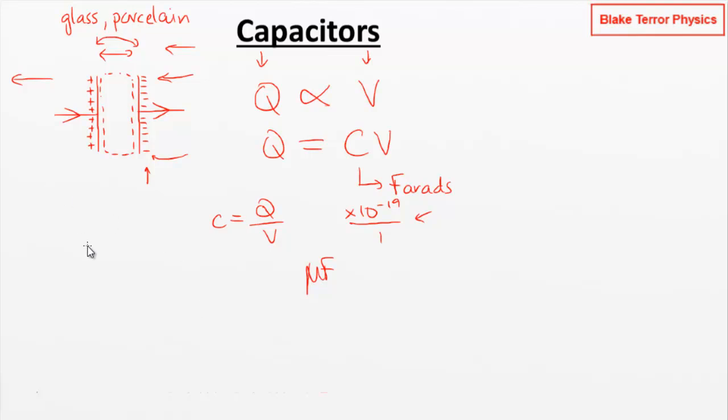The one thing that really does affect it is the effect of voltage on the dielectric. What this dielectric is doing is allowing us to store more charge on the capacitor plates. So we're getting a higher charge storage capacity by having this dielectric there. Although it's insulating and blocking any current flow between the plates, which is what we need in order to get this potential difference between the plates, in order to store that charge, in order to build up the energy that we're storing on this plate.